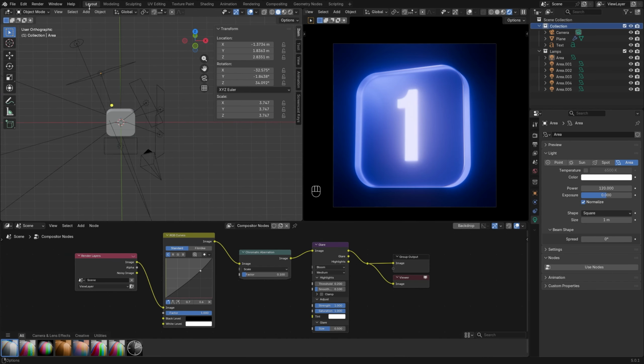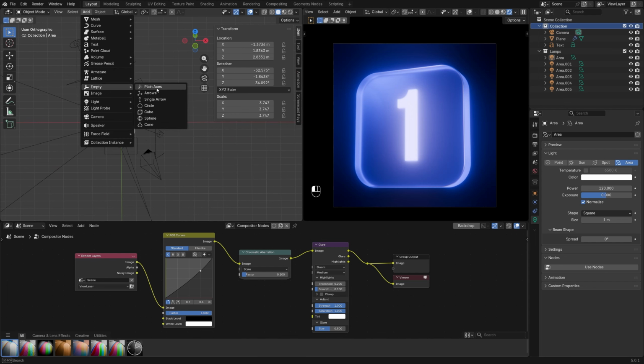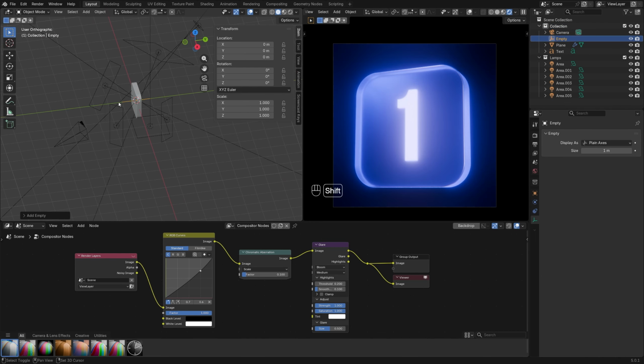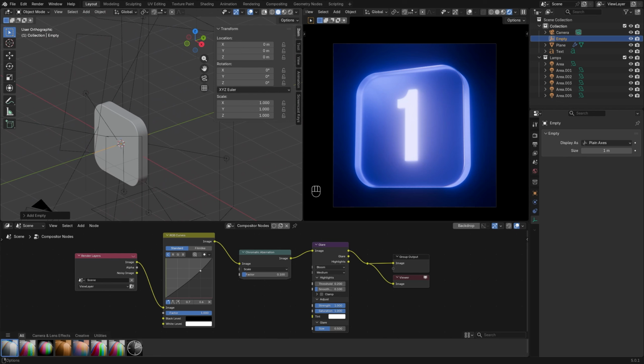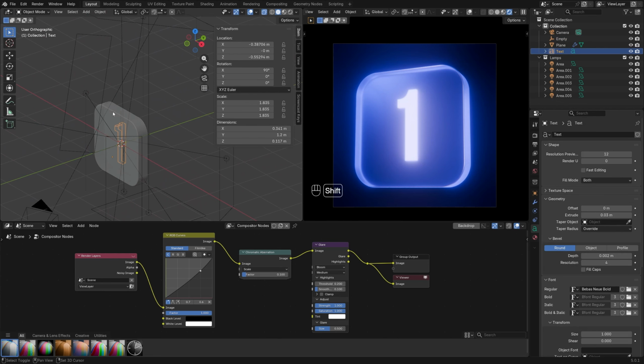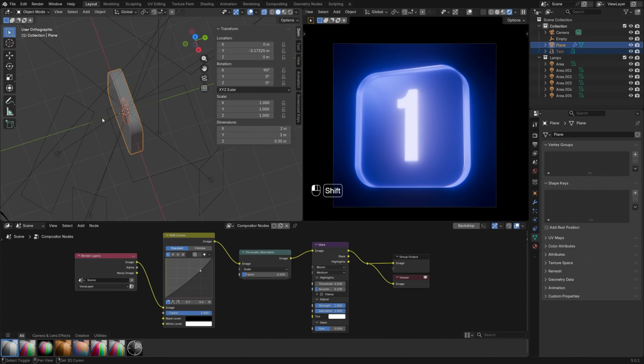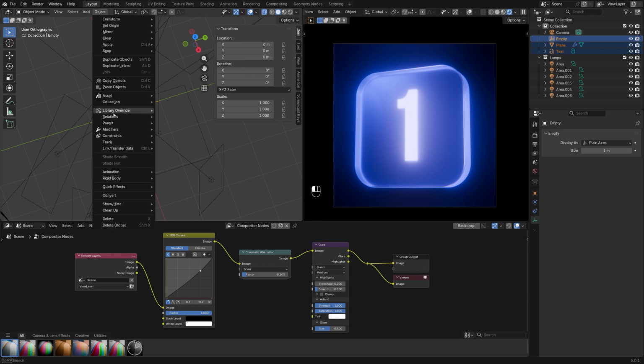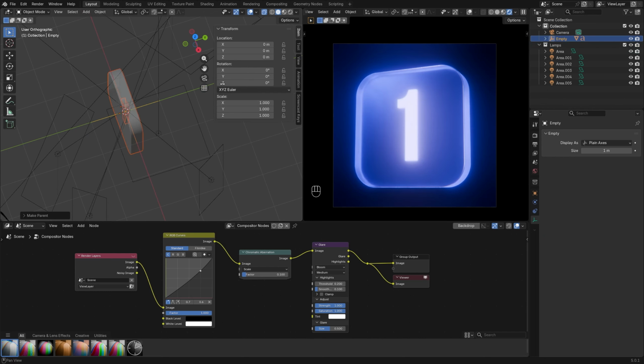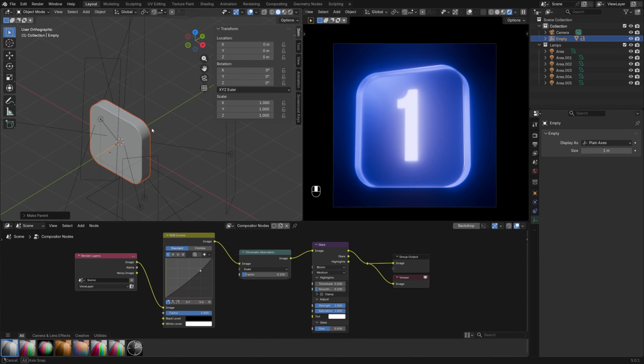We'll then add a so-called dummy object to the scene. We'll enable transparency, then select both of the objects, and finally, the empty object itself. After that, we will parent these objects to the empty, and they will begin to replicate all its transformations.